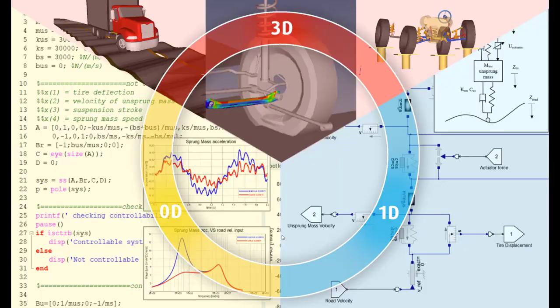This idea of modeling in a 0D, 1D or 3D manner I'll talk about a little bit in the upcoming slides. Just to hit on it again, 0D is the mathematical approach, or a system of equations to represent a mechanical system, let's say. A 1D approach would be that drag and drop block diagram system modeling way. And then the 3D would be if you're co-simulating with a model-based tool, a 3D model, and using that as a subsystem in your system model.